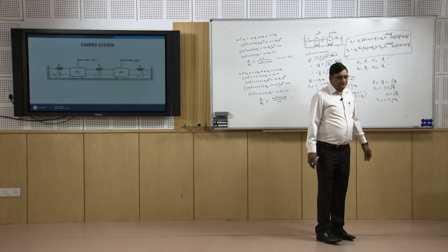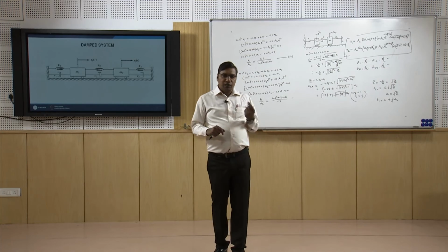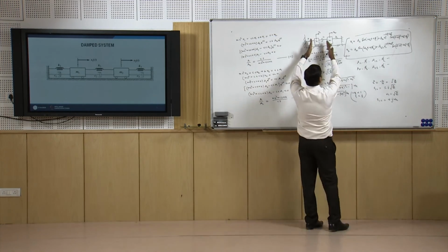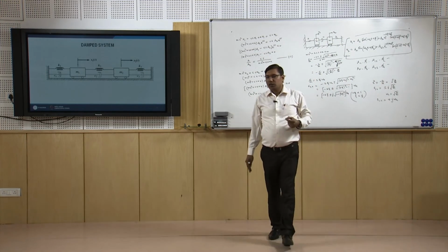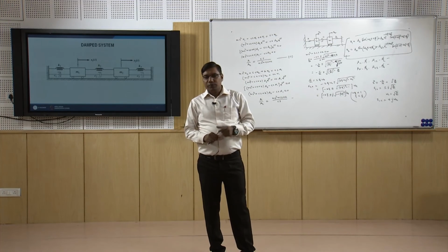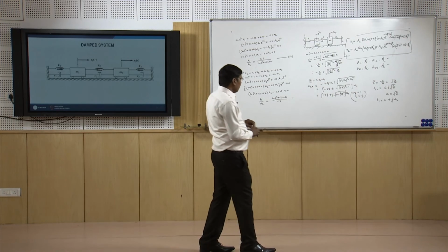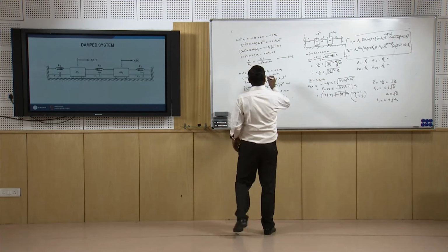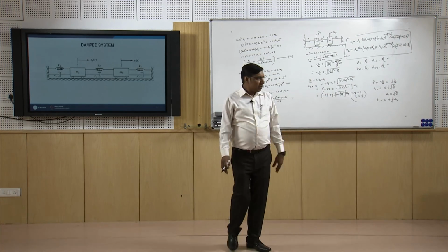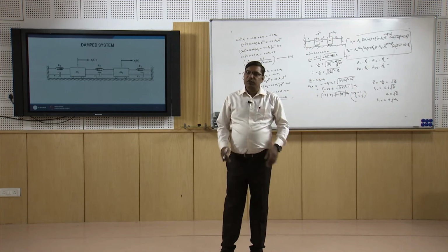Now, if the system is given an equal initial disturbance, so if initially we displace both masses with equal amplitude, like 5 mm both, then the system will vibrate purely with the first natural frequency, because from here we get the mode shape corresponding to the first natural frequency and the mode shape corresponding to the second frequency.